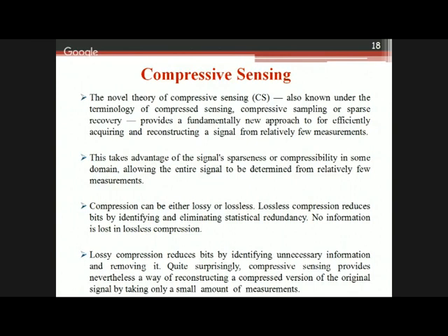So once you do that, in order to reconstruct my original signal, of course, if I'm dealing with the real world, I need my data to be in analog form. So when I have to convert my digital data back into the analog form, I have to follow this criteria, that is the Nyquist criteria, that is Fs, your sampling frequency, needs to be greater than or equal to 2Fm, and this is called your oversampling. This is what I have told you is critical sampling.